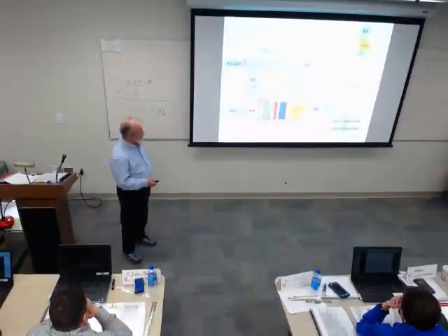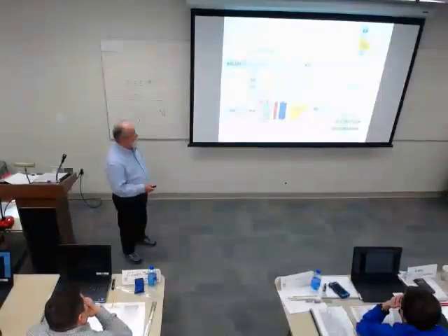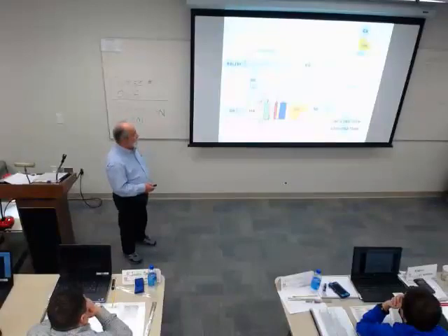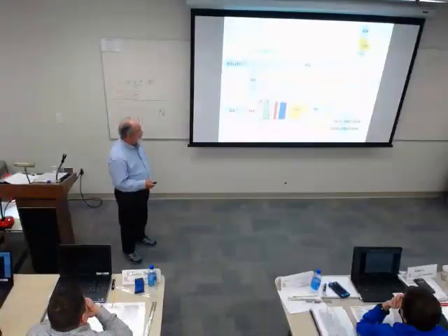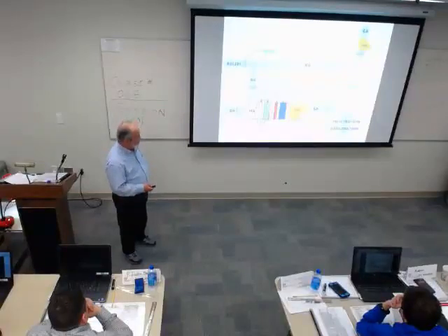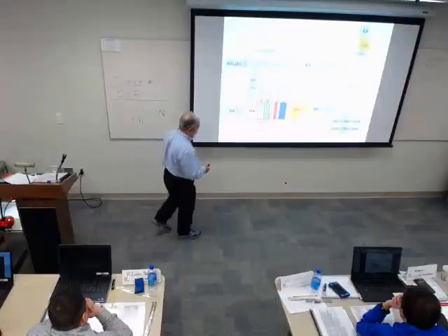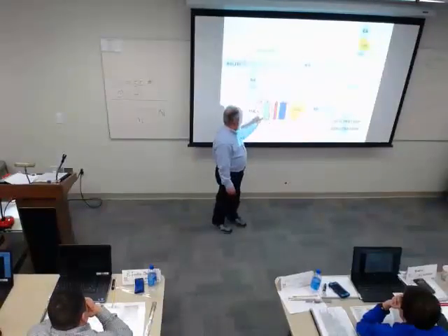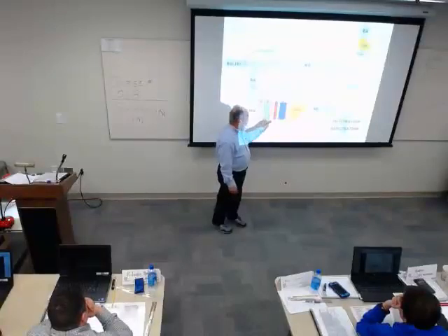So we're back at our system again here. We've got an exhaust air fan taking some air out of the building. That runs usually somewhat constant. There are intermittent ones depending upon its function. And we've got the pre-filter, the filter, and we've talked about those. Those are the ones where our current approach is MERV 8 here, and MERV 13 there.